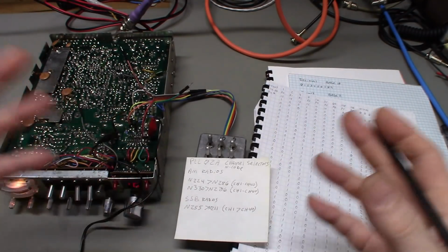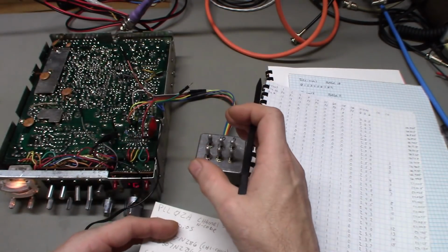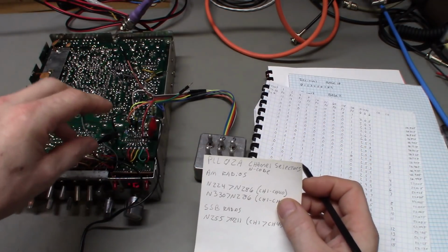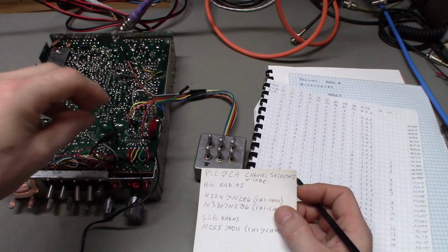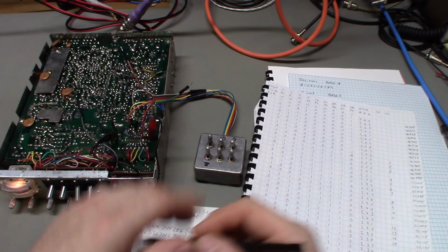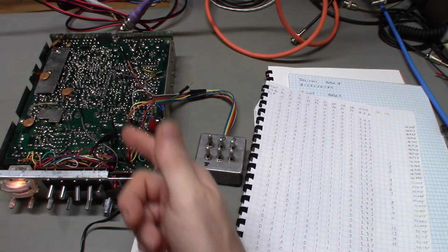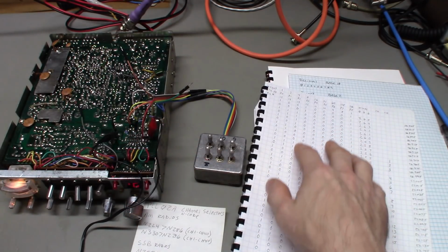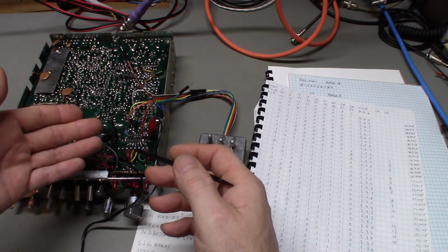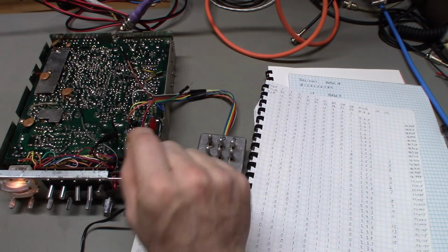There's lots of different ways of doing it. That's one method. You can pull a channel selector switch out of a different radio and play around with it. You can use channel selectors even from radios that don't have a PLL02A in it. You would just need to buzz out those switches and see how those rotary switches are basically programming the PLL. You'd need to make up a truth chart for your channel selector switch, and then you would know that's the truth chart for the radio, because that's what that channel selector switch is actually sending to the PLL.